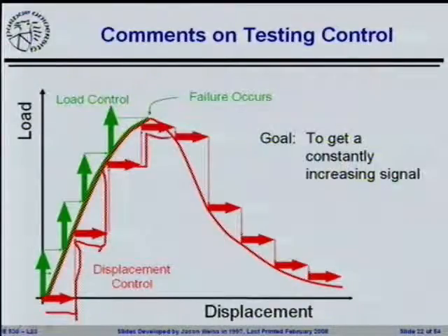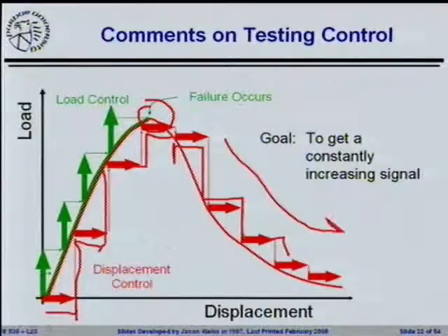Apply another displacement. Now all of a sudden, what you see is we've gotten rid of the instability that occurs around the peak. The specimen would, in theory, no longer explode. You could now increase the displacement, measure the load, increase the displacement, measure the load, go the whole direction out, and trace out the entire stress-strain behavior.